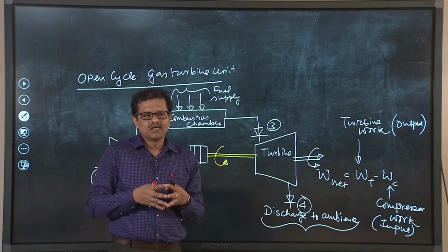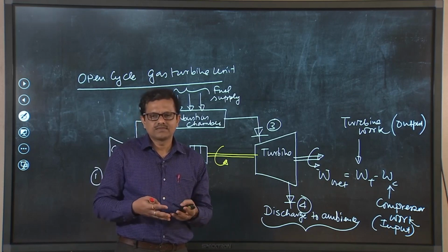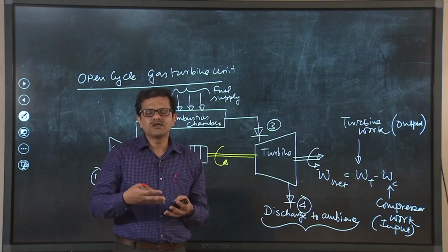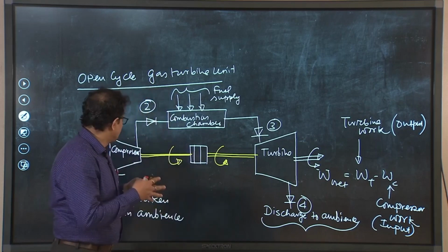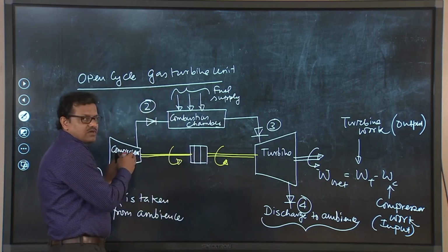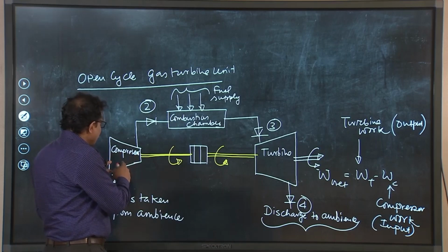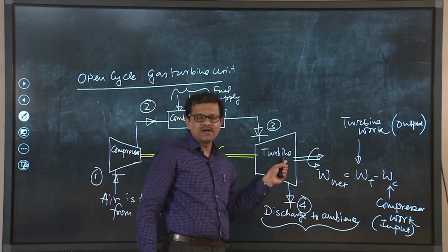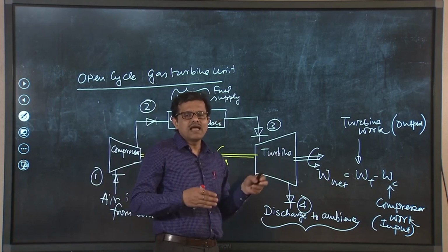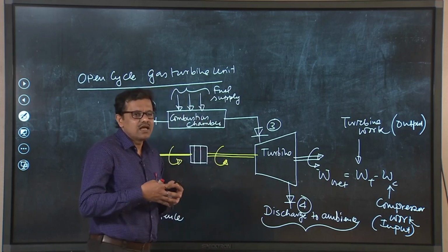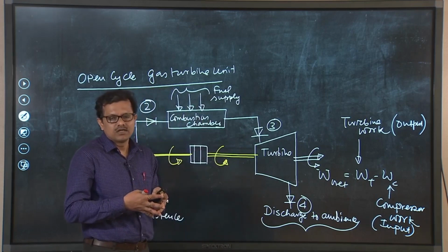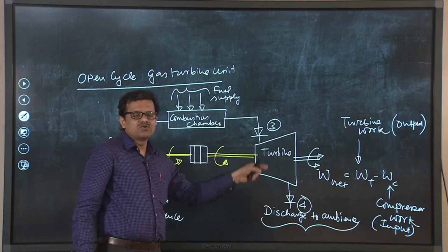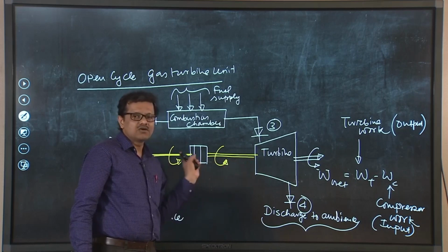The question is, here the working fluid is air or gas. Now, the specific heat of the gas will vary because it is a function of temperature as well. So, we have to assume that when the working fluid is getting compressed in a compressor or expanded in a turbine, we can certainly consider an average value of Cp and also gamma to measure the performance or to measure the processes that are there in a compressor or turbine.